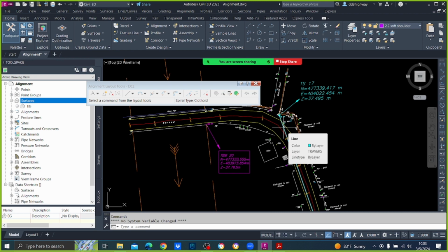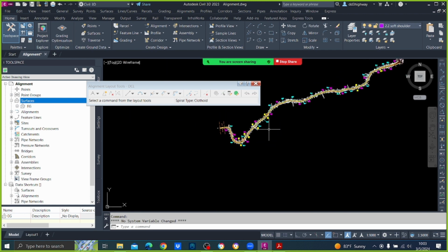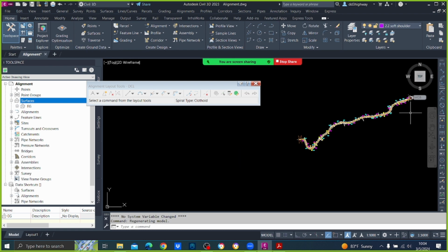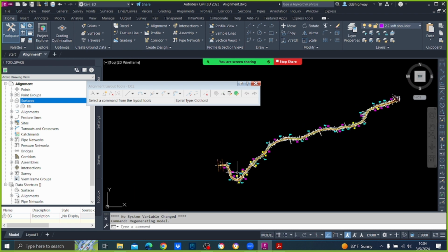Of course, if you are going to do a design, how do you select it? One thing is, from the feasibility study you get what the design speed is, 50 or something. Otherwise, what we do is we have a brief look at the alignment and check what is the maximum curve radius, maximum in the sense of the reasonable curve radius that we can go. Usually we try to design at least up to 50 kmph, but there are some exceptions.